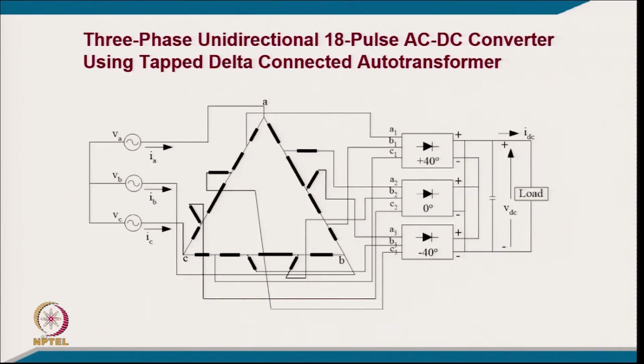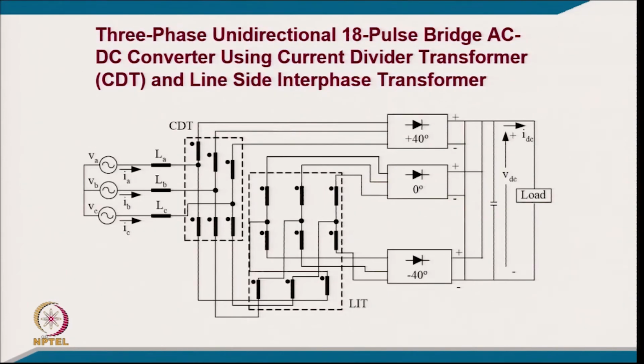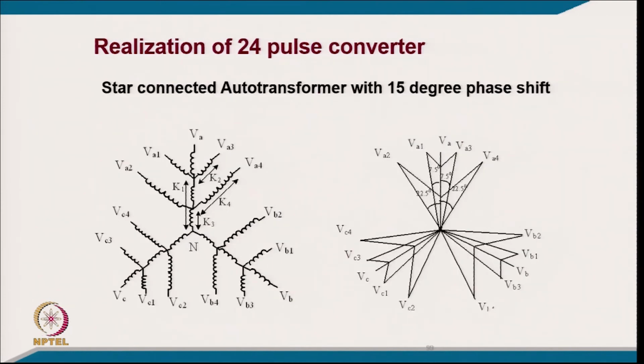And this is typically another way to get 18 pulse: to convert 3 phase into 9 phase, and then use the 3 bridges corresponding to phase staggering. So, here we are converting to multi-phase, 9 phase, an odd number of phases, so that we can convert 9 phase into 18 pulse using the 3 bridges. So, that is the multi-phase concept, and how we are designing for this multi-phase.